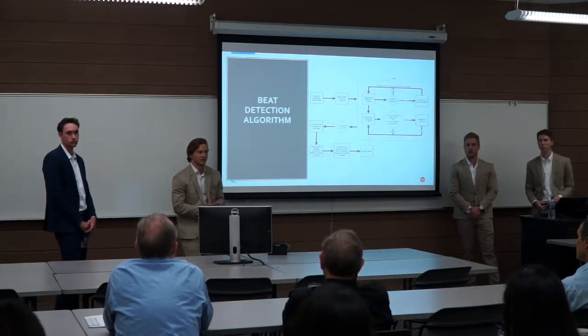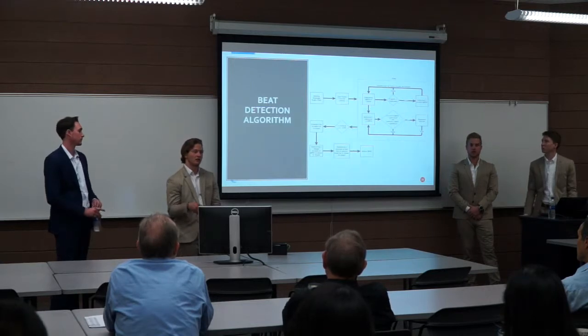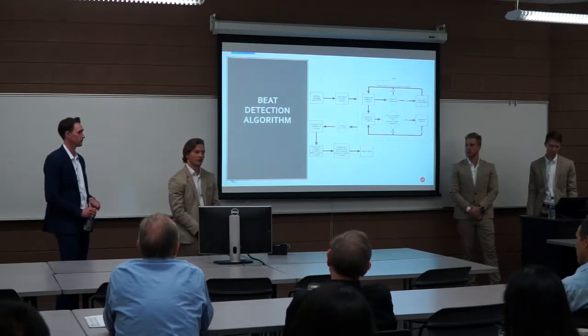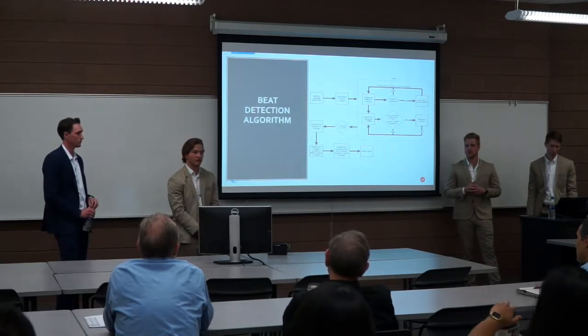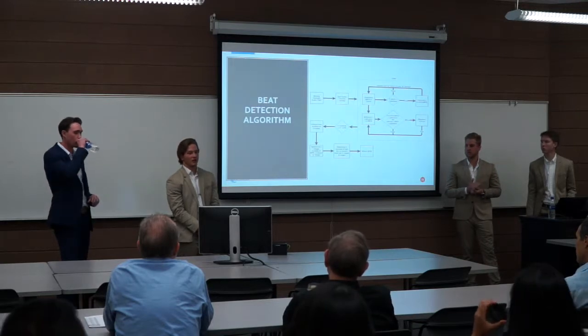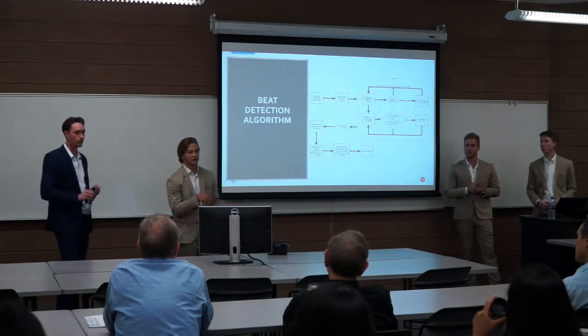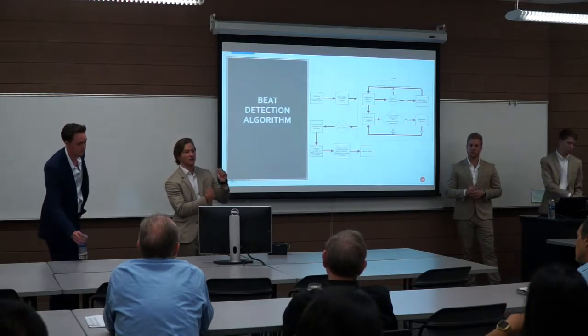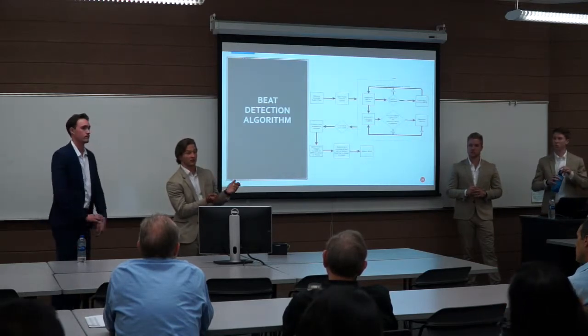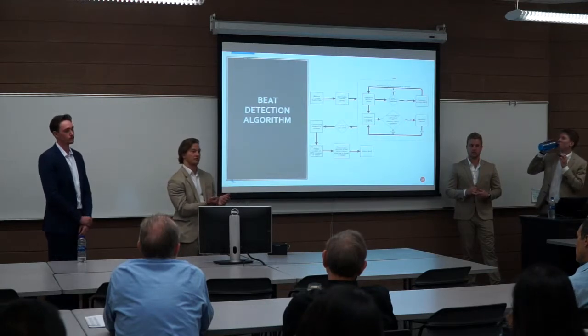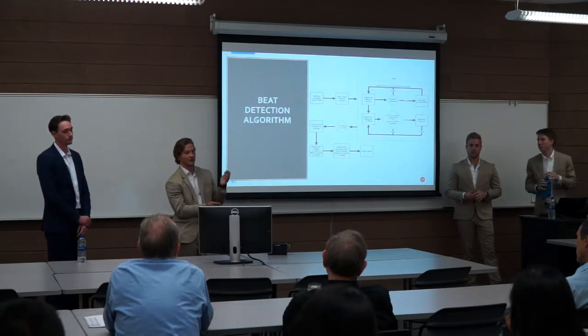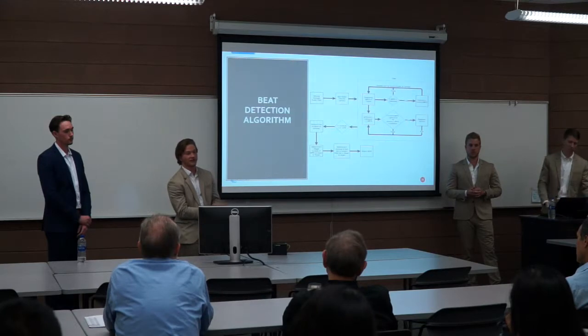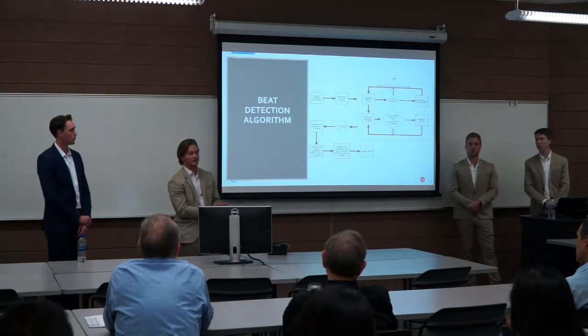Seward here, because we actually talked about that last semester. The sampling information coming into the buffer, the actual mic itself, was getting filled too quickly and we were getting overrun. What essentially happened was it was causing these giant spikes that were totally random in our actual wave files themselves. So the beat detection algorithm was getting fooled, thinking that was a hit with the kick drum because it was such a high dB level that it was confused.